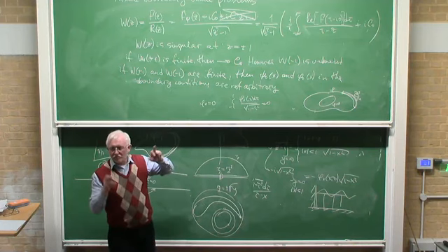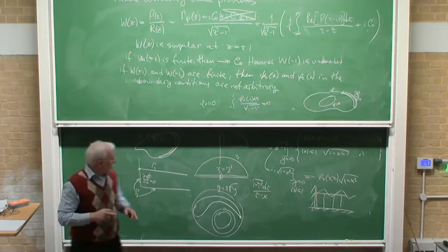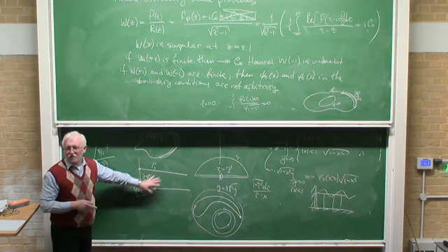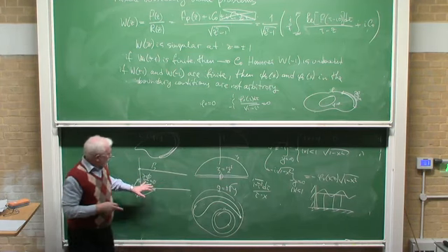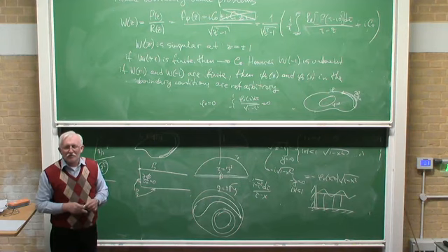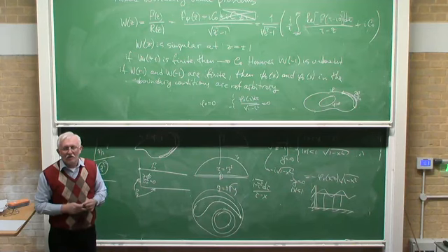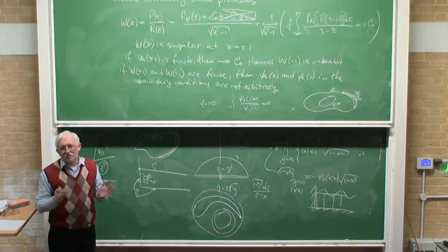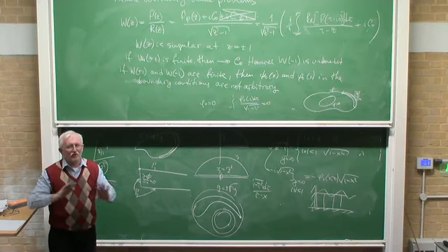In our problem, we consider there are 2 points. However, as I said, this technique suggested conformal mapping onto special domains like that, and then we can use separation of variables. Actually, you can use the stream function and the potential as variables, no? Because the stream function is equal to 0 on both walls. Yes.